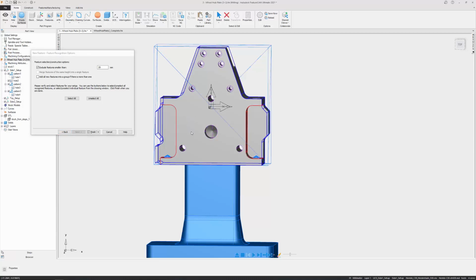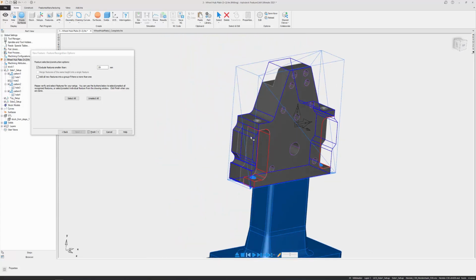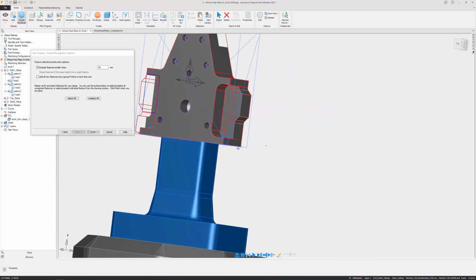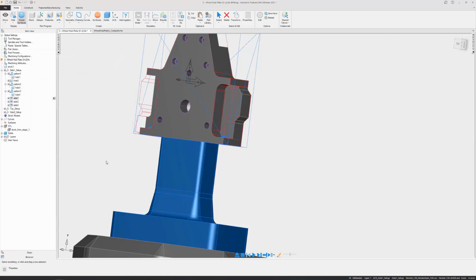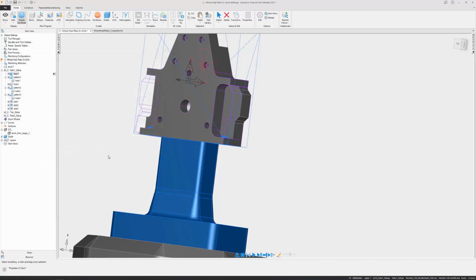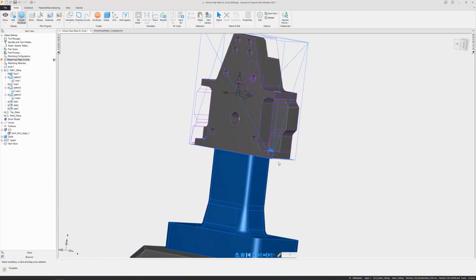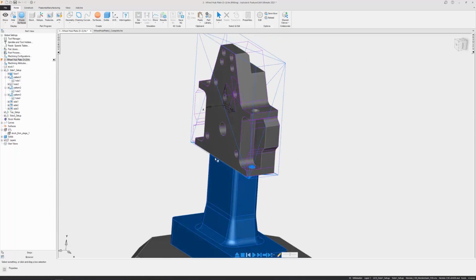I like these two. We definitely want to be machining those, and a side feature seems appropriate. It also looks like it's gotten this outer profile. And we'll leave it at that for this setup. I think finally I'll just throw a face at Z equals 0 here to machine down to that front face. And we have our first orientation, I believe, fully programmed. From here on out, it's just rinse and repeat with each one of the additional orientations. And that's really all there is to 3+2 machining.